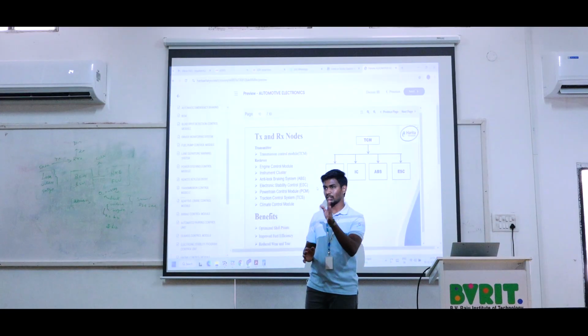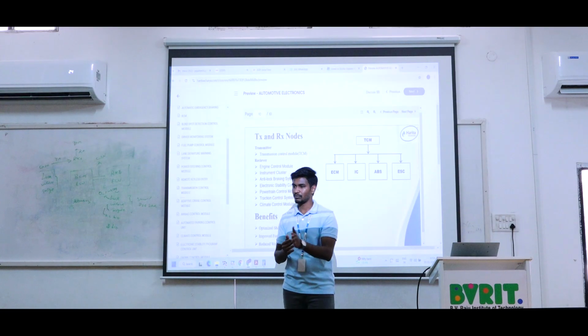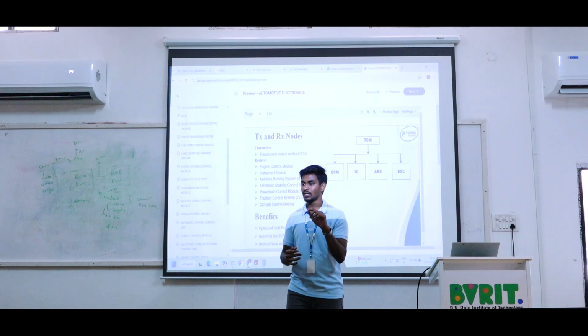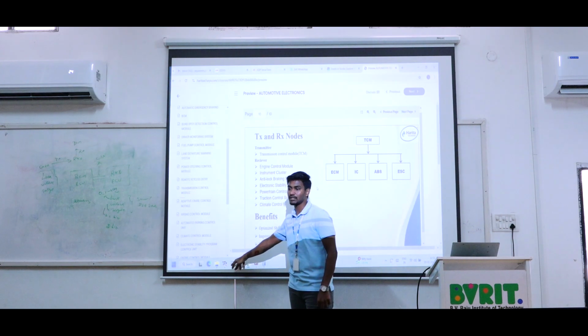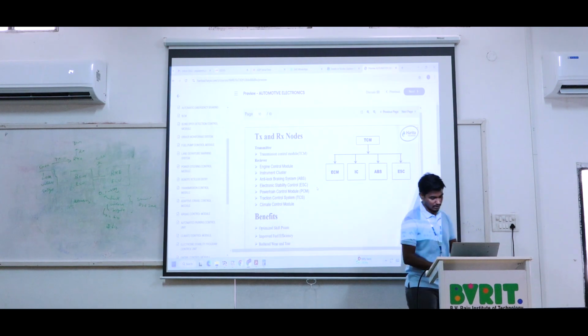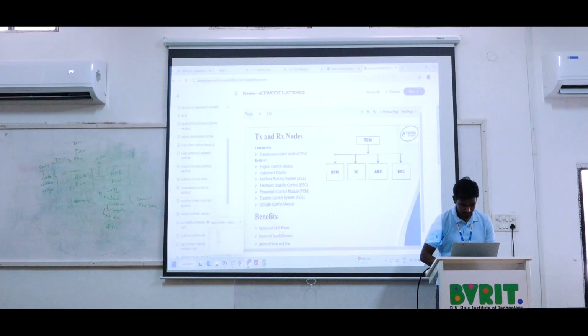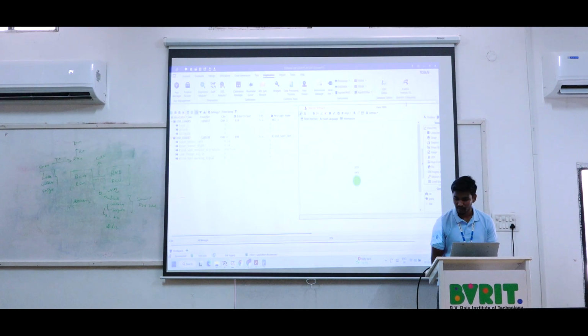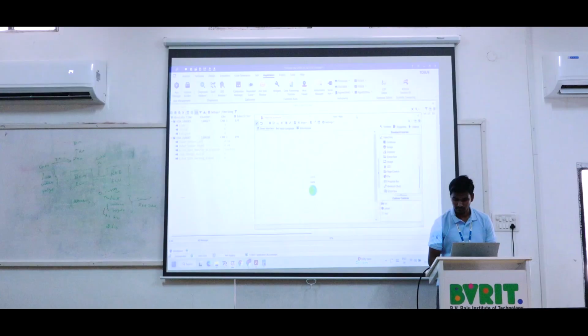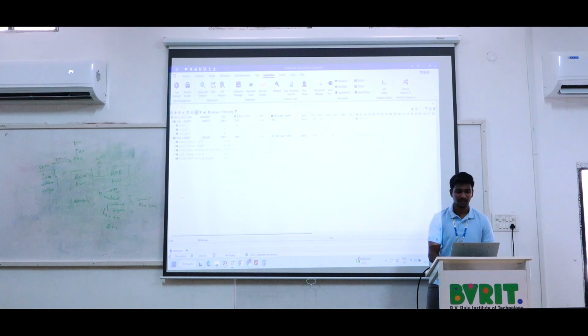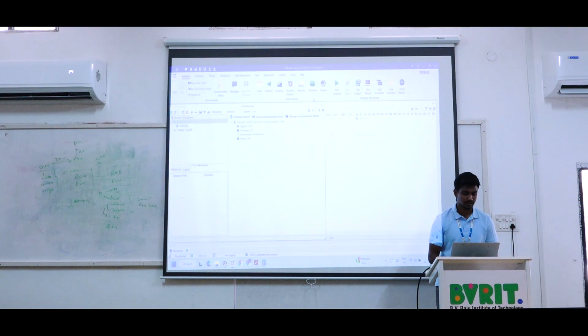For a working car there is no issue, but at service time we face some issues. Without a database we will not get anything proper. Here I have uploaded the database, just as an example, so that we can easily know what it is: which CAN channel it is from, that it is an RKE message, and so on. If I don't upload any database and transmit some message, we will definitely not get any output like this. Is that correct or not?